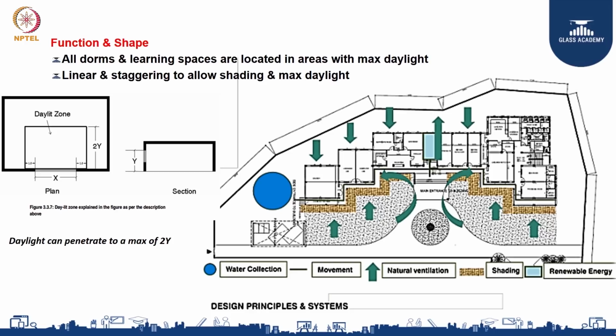When I say functionally placing certain spaces, let me take an example of an academic building. We have an auditorium, we have classroom spaces. An auditorium ideally does not require windows, because you have to make sure that the audience focuses on the stage, and you will have its own set of lighting. So you do not need to place an auditorium at the periphery of the building. Whereas for classrooms, you need to make sure that students or children have access to views and daylight. So how do you position this inside your building such that there is a benefit because of the functional spaces you have allocated?